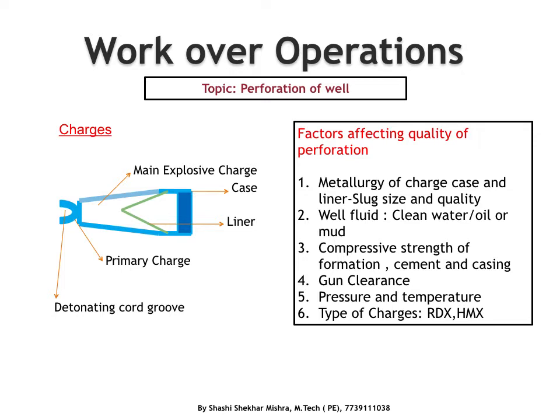Then comes the compressive strength of the formation and also the strength of the cement and casing. The jet penetrates deeper with less compressive strength of the casing, cement and the formation. So with the increase in strength, the jet penetration reduces.